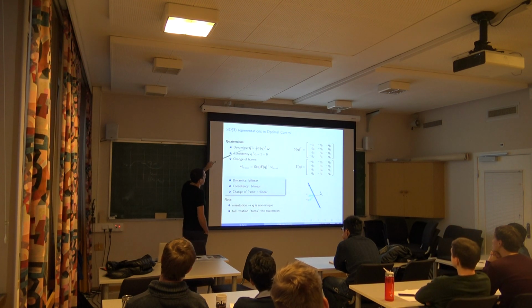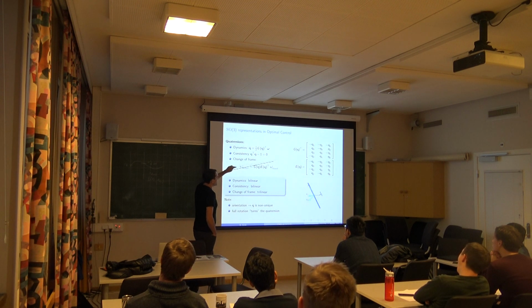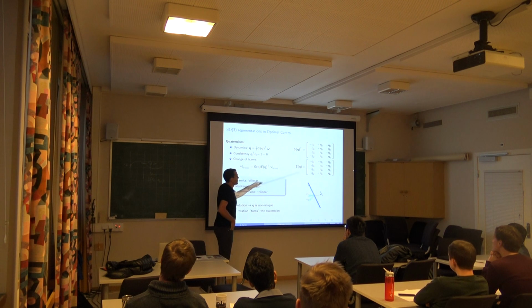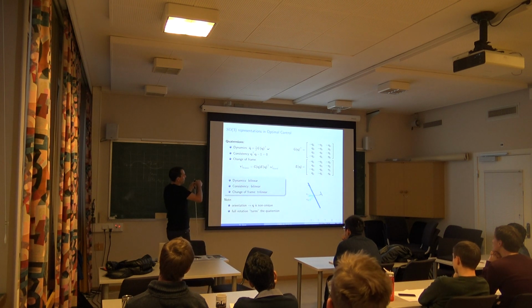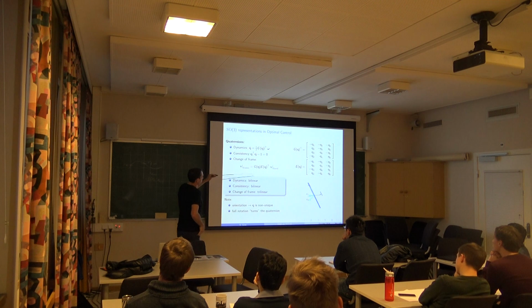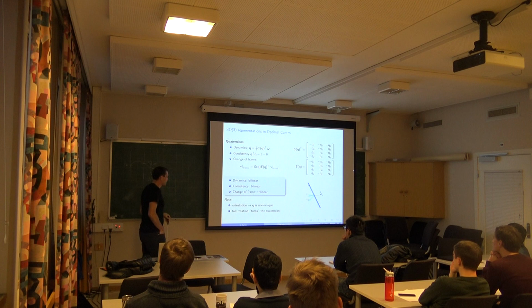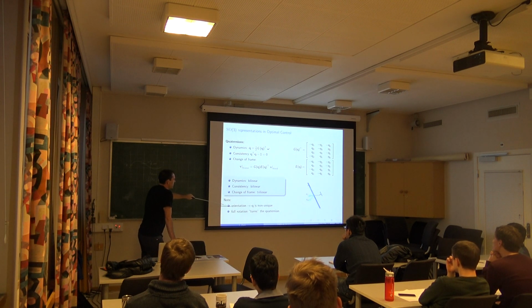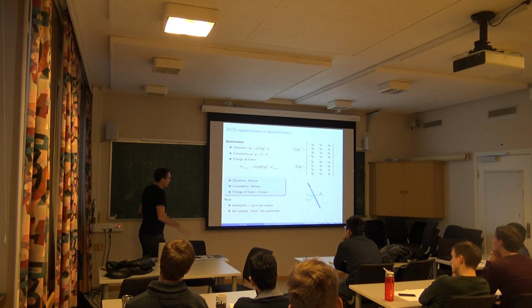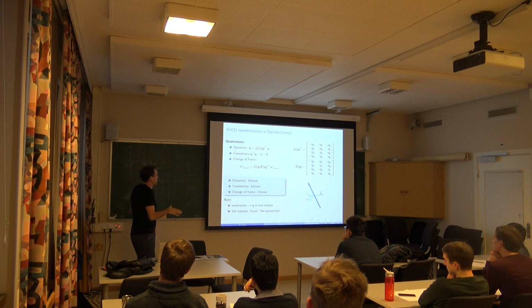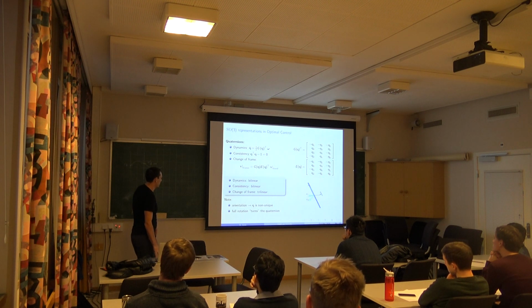The dynamics are not that complex. You have also some consistency conditions, and if you have changes of reference frame, you need to form this trilinear product. So you have essentially terms that involve three multiplications between different states typically. So with this matrix, that matrix, and maybe your velocity. Yeah, you probably know that. So the quaternions can be a bit annoying to work with. For example, for a given orientation, you have two quaternions that represent that. So sometimes it's a bit annoying.